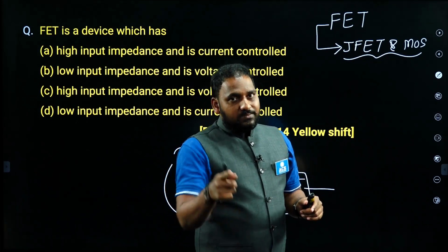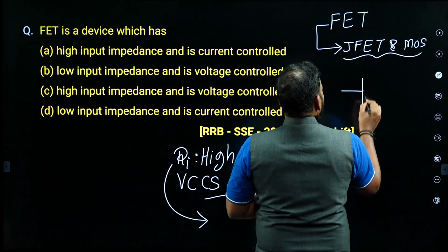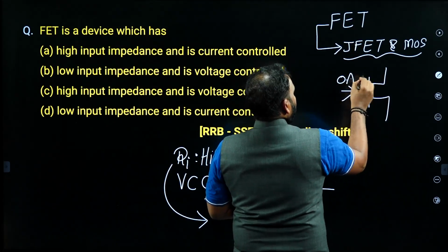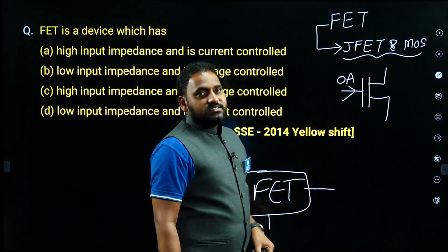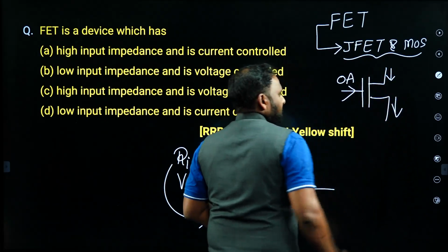Next objective bit I am giving you. In FET and MOSFET, generally gate current is 0 under ideal conditions. In JFET, the gate junction is reverse biased, so current is 0. Always source current is equal to the drain current, okay? So these are the extra points.